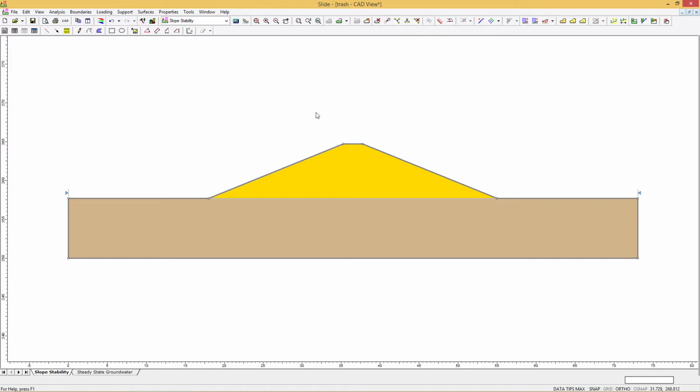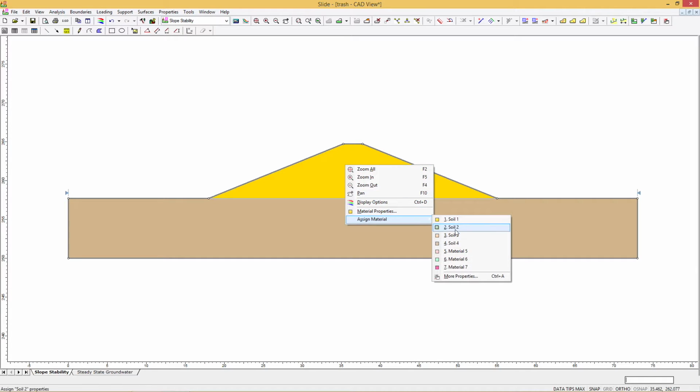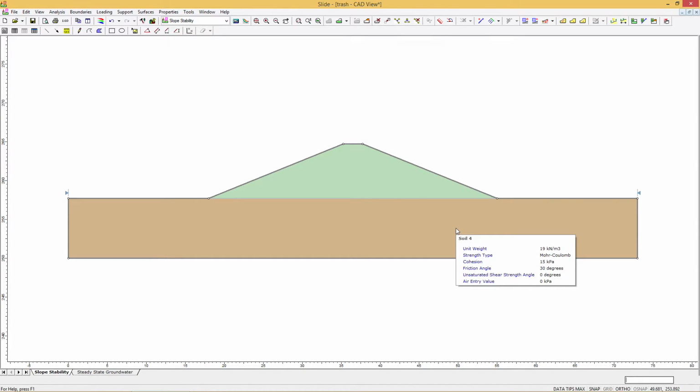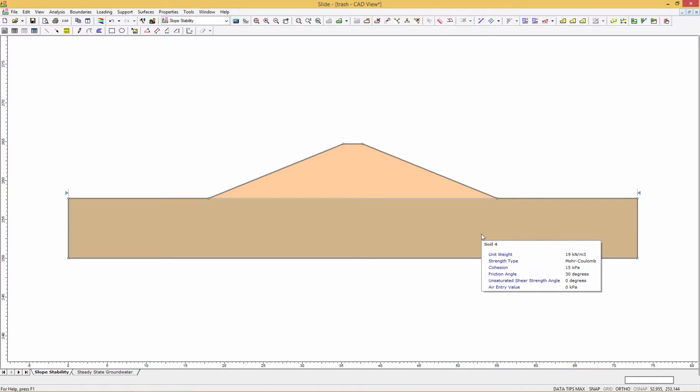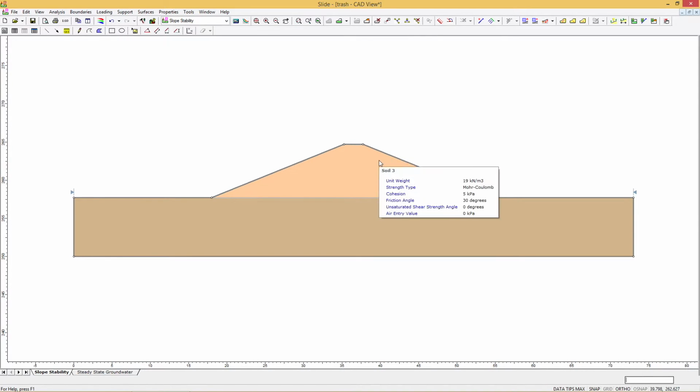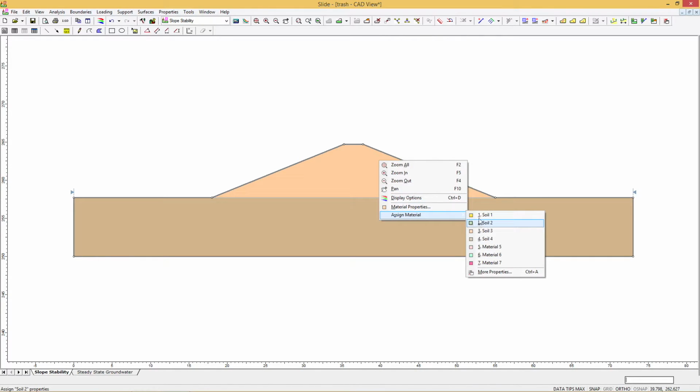Any question? Once you finish the project, the only thing you have to do is create a copy of that file, open the file, come to the material properties and say, change the material to soil 2, and run again. Do the same and change to soil 3. Okay? Now, this is just geometry and materials. Let's go to, this is soil 1.